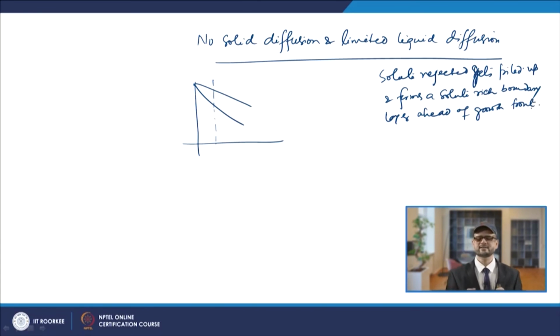In this case the equilibrium will exist only at the interface, because you have limited liquid diffusion as well as no solid diffusion.